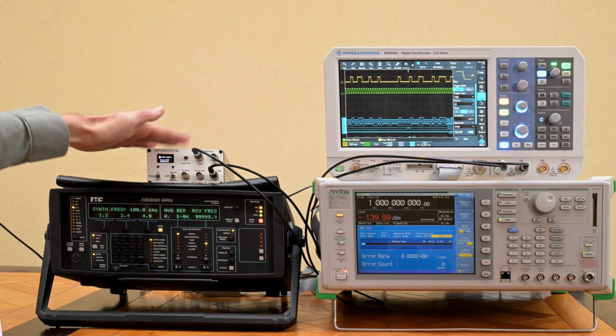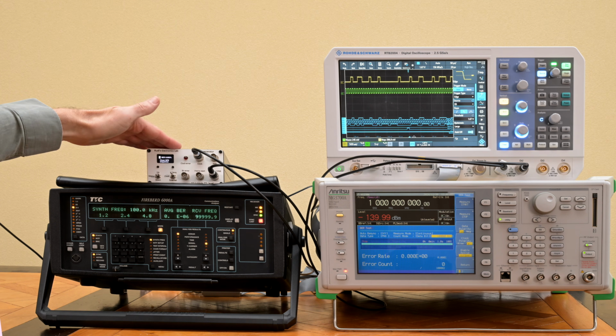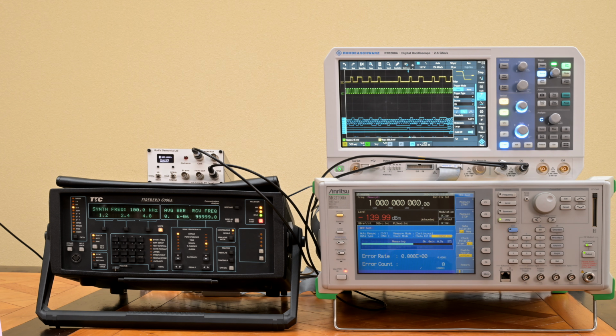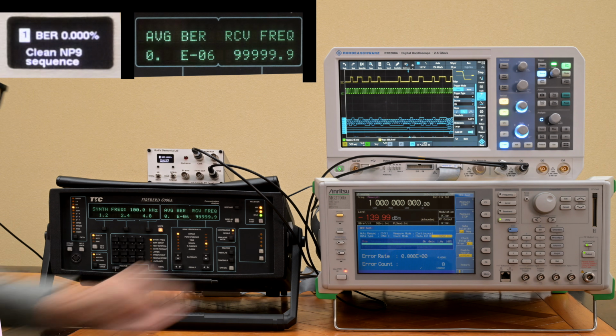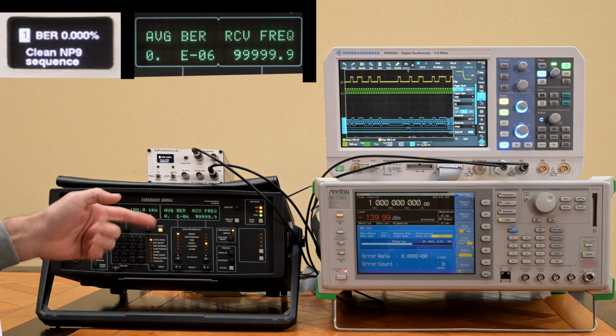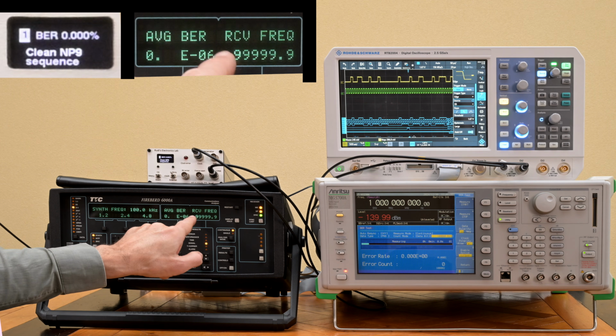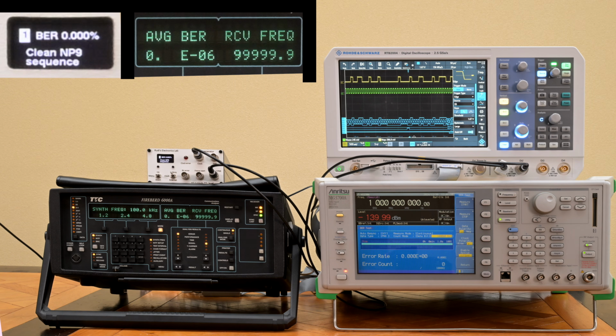But of course I'm super excited to see whether the Fireberd actually properly receives the signal from my homebrew generator. So I connected it up. I basically configured the device to the code length, which is PN9, so 512 minus 1 is 511. And I've also been setting up the Anritsu at the same time, so it's measuring the same signal here. And right now we're seeing 0 errors. We are synced. We see 1s and 0s, and there are simply 0 errors coming in, and it's noting a frequency of 100 kilohertz, which is correct. That's the internal default frequency of the device.